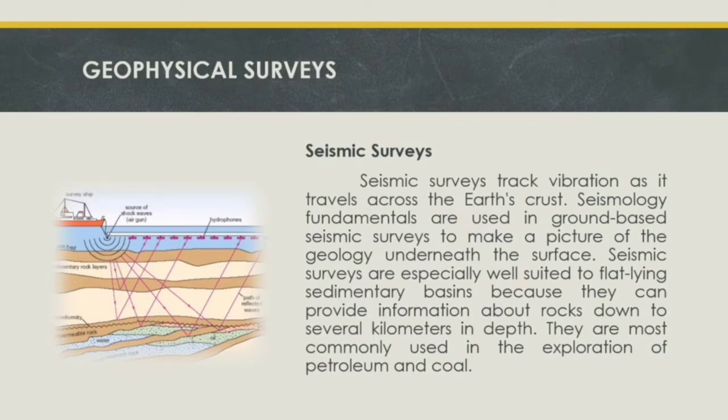Seismic surveys. Seismic surveys track vibration as it travels across the Earth's crust. Seismology fundamentals are used in ground-based seismic surveys to make a picture of the geology underneath the surface. Seismic surveys are especially well-suited to flat-lying sedimentary basins because they can provide information about rocks down to several kilometers in depth. They are most commonly used in the exploration of petroleum and coal.